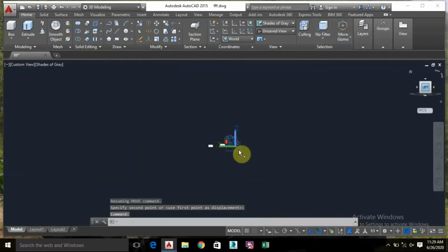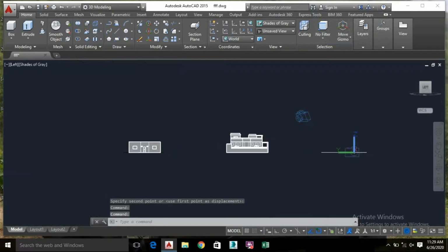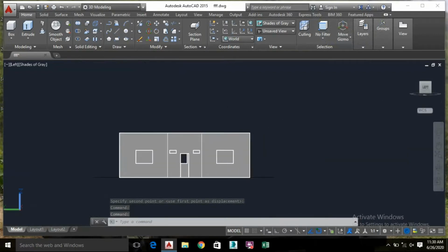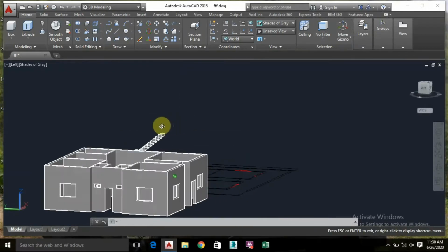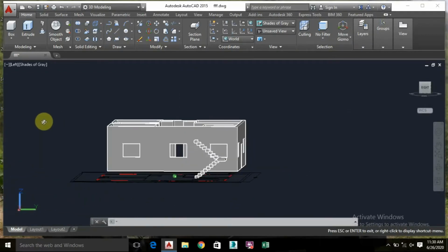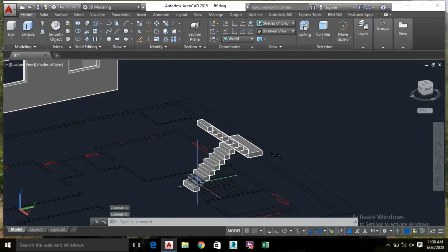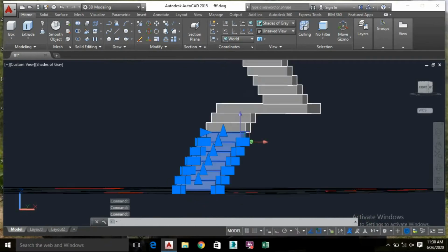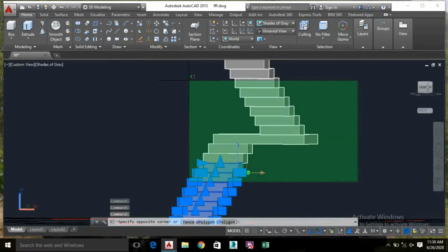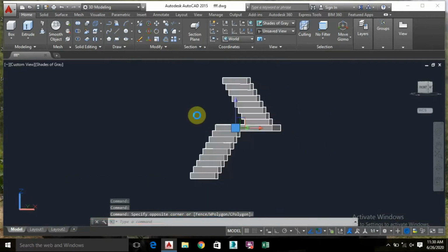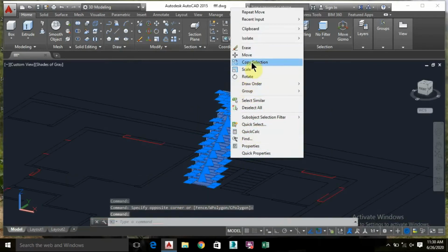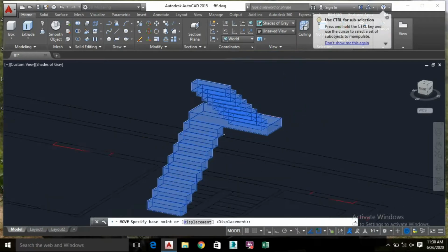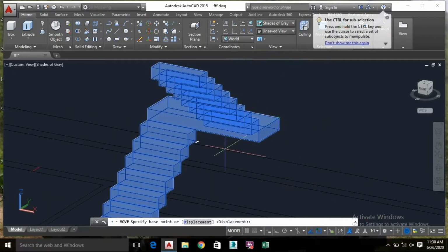Okay, you can also check the level of your stairs if they are somewhat downwards or upwards from your first floor level. Now I will just move my stairs and check if they are getting fit in this or not. Just select them one by one. Just pressing shift, I will capture them in my screen, and now I will move this, giving this point as the reference point, and I'll make the ortho on.